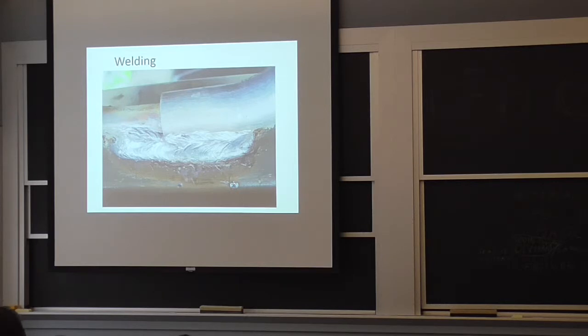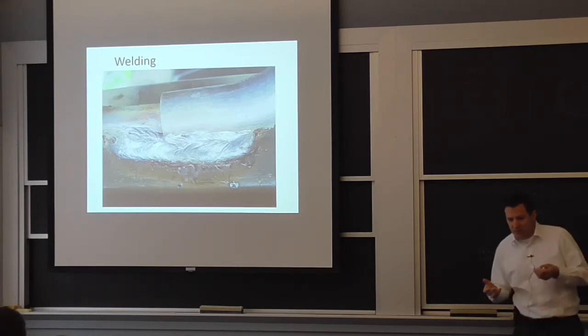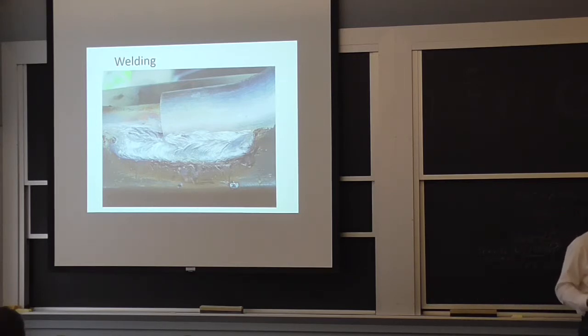So welding is used mostly for efficiency. In terms of structural aspect, if I'm a simple mechanic, I like welding stuff because after they're welded, they don't move. The bolt doesn't get loose. I don't have to worry about it. But when we're talking about a very critical application, say in aerospace, they really, really don't like welds because they're not the strongest in repeated loading.